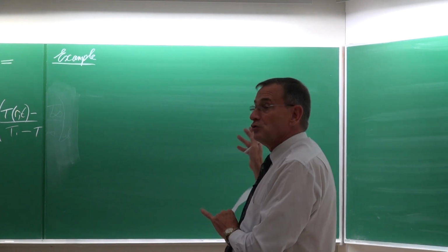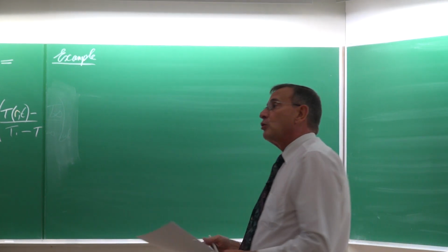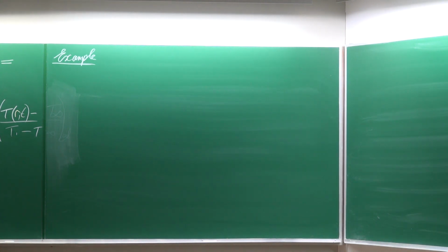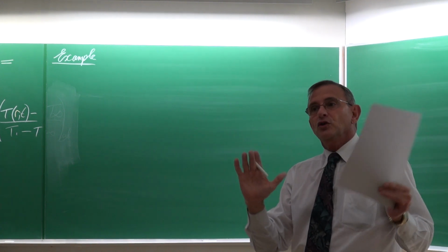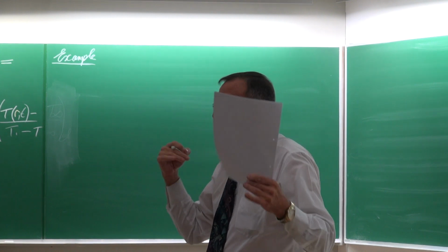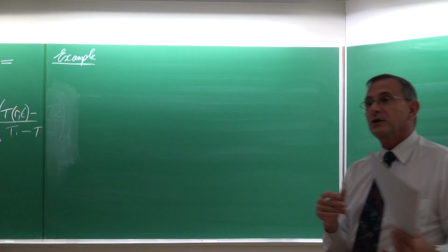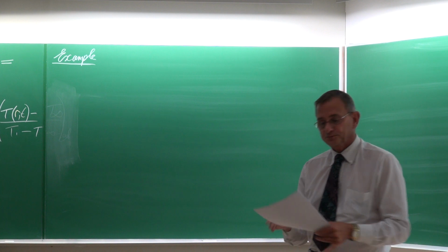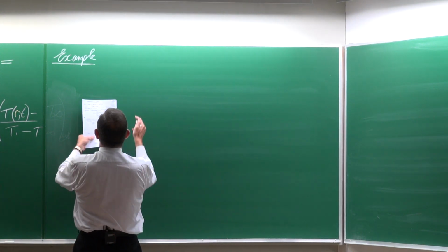I'm going to use the solutions from the Heisler charts. Why? Because the mathematics becomes very challenging firstly to do in 2 lectures. Normally I take 2 lectures to do it. And then you do not really follow what is the principle. So really to illustrate the principle, I'm going to use the Heisler charts to get the solution every time. So the example that we are going to do is that of a short brass cylinder.